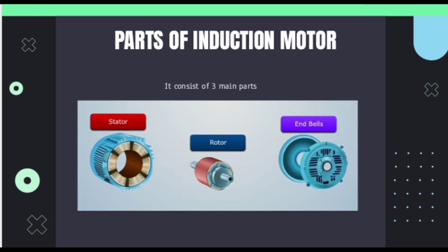The rotor is the central component of the motor and is attached to the shaft. The rotor, usually of copper or aluminum strips, is attached at each end to a circular attachment. This configuration is called squirrel cage rotor because of its appearance. The magnetic field generated by the stator induces a current in the rotor, which in turn creates its own magnetic field. The interaction of magnetic fields in the stator and rotor results in a mechanical torque of the rotor.